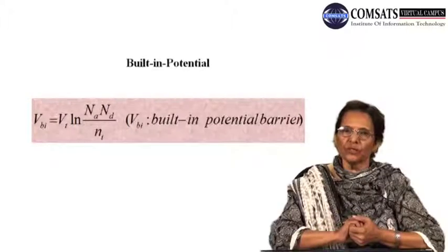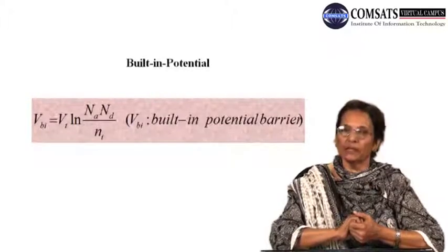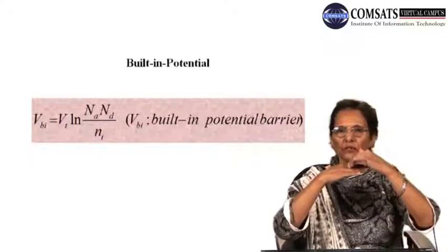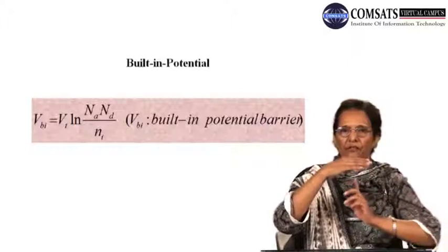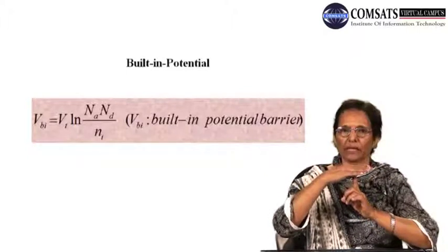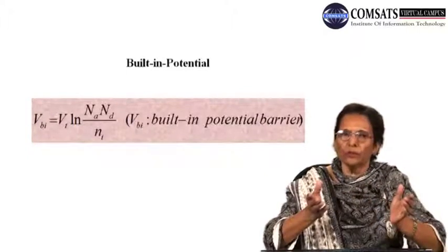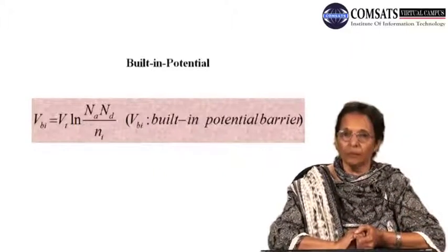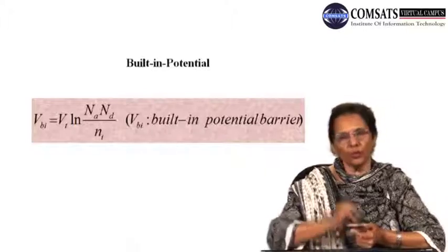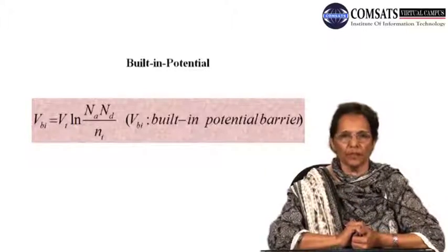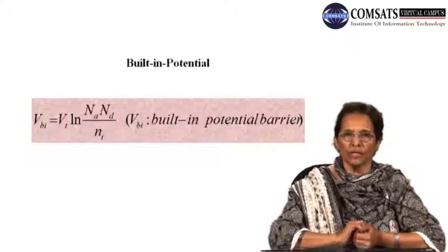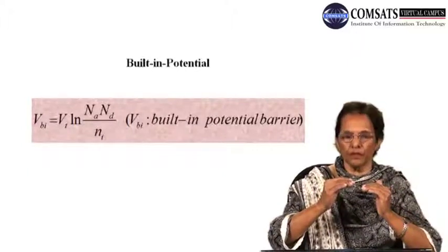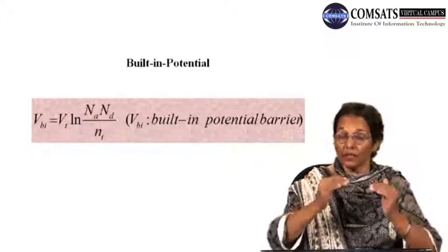This carrier concentration is again in the pure or intrinsic material, the free electrons in the conduction band and free holes in the valence band. Where do they come from? Because we have not doped the semiconductor material as yet. They come from another process which I defined previously, thermal generation, because we are holding the device at room temperature, 300 Kelvin.